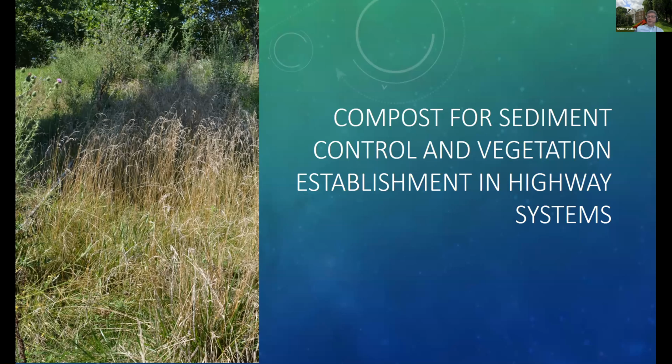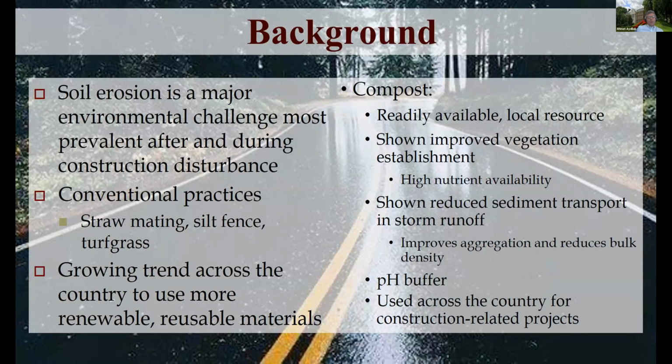The second study that we looked at was compost for sediment control and vegetation establishment in highway systems. We were looking at soil erosion in our applications, and soil erosion is a major environmental challenge, and that encouraged us to look at this problem. Conventional practices use straw matting, silt fence, turf grass, and there's increased interest in using renewable materials. Compost is one of them.